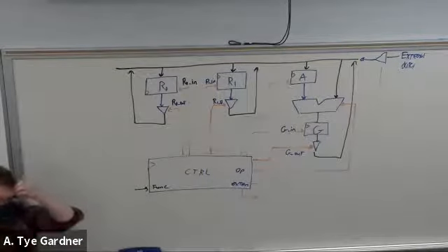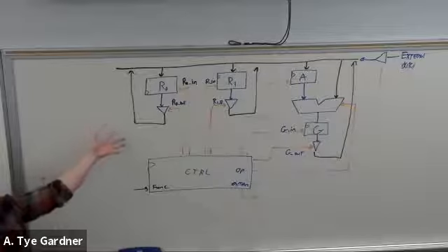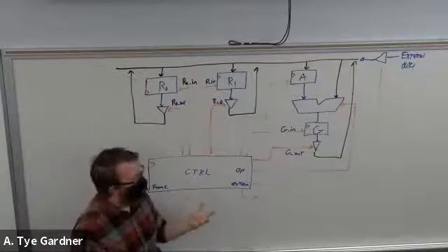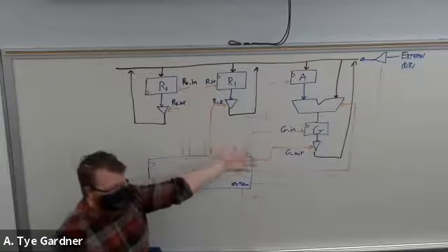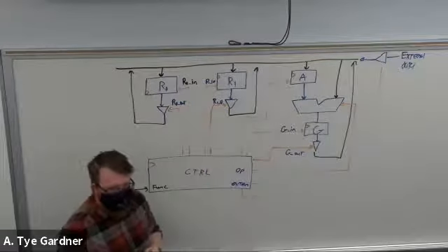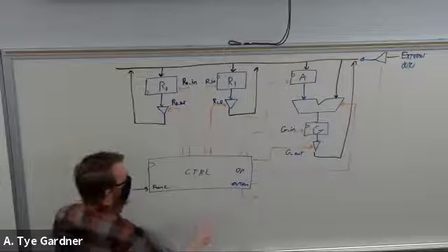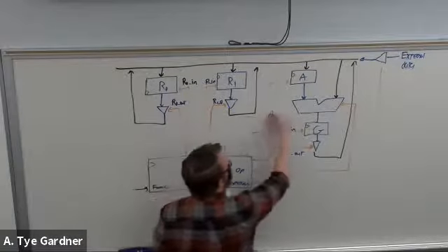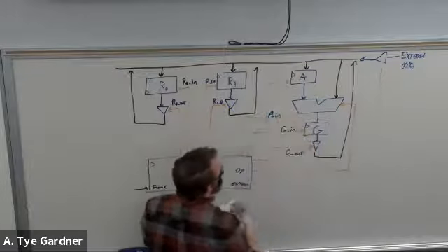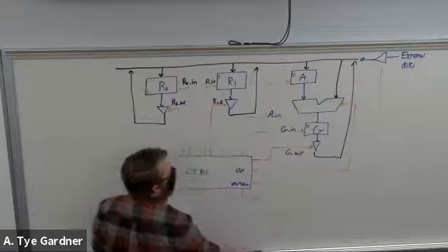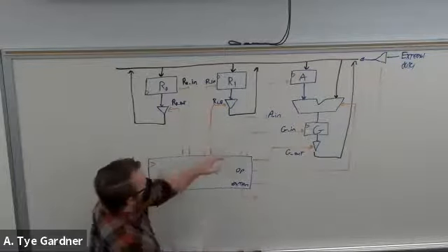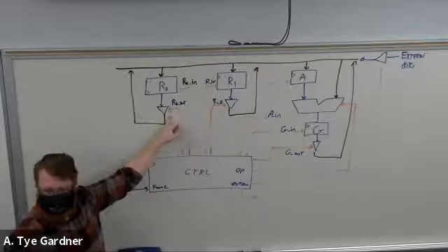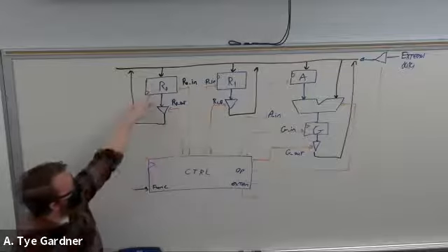Well, now those are in those memories, I can do something with them maybe, but in order to add them, I need to get them to the ALU. So what I might do then is assert this signal, the A in, so that on the 3rd clock cycle, I will assert A in and R0 out, so that the bus is driven by this 3.